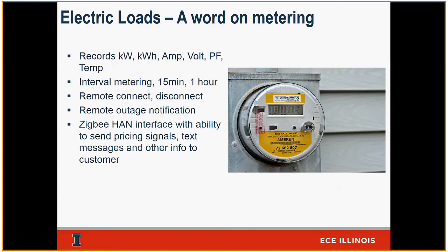Or unless a big fault happened, like we said last time. If a big tree comes down and breaks a line, then you know an event happened. But if something happened in my backyard and something went bad and I'm out of power, I had to pick up the phone and call. Well, an AMI meter has that capability today. As soon as it loses power, it sends a loss of power message back to our systems, and I would know a customer has lost power.